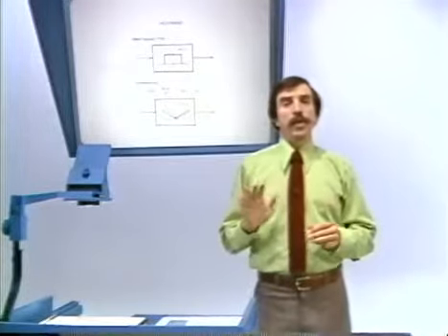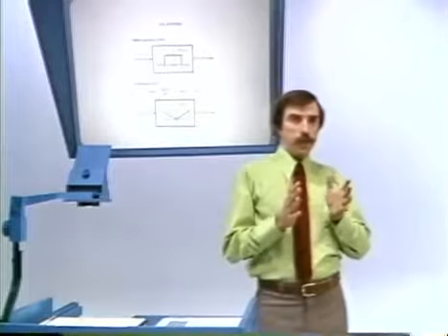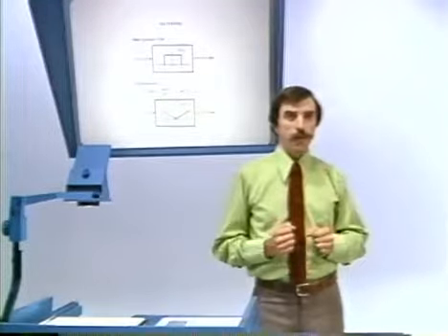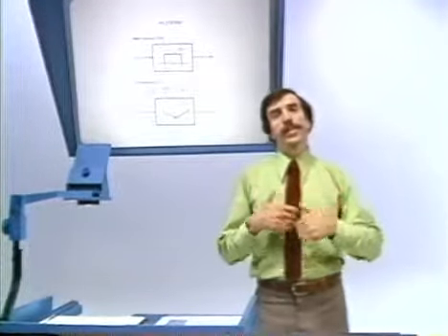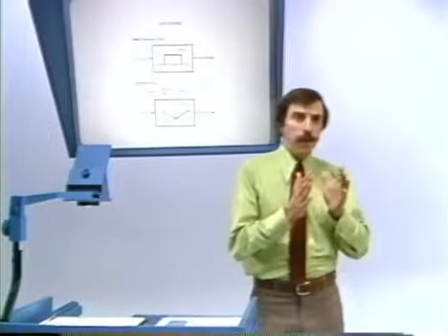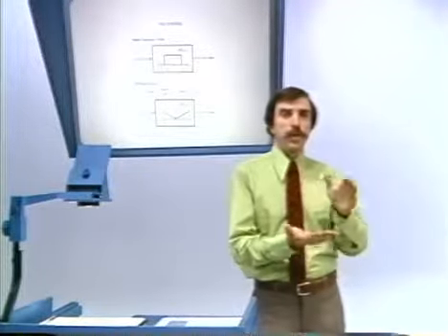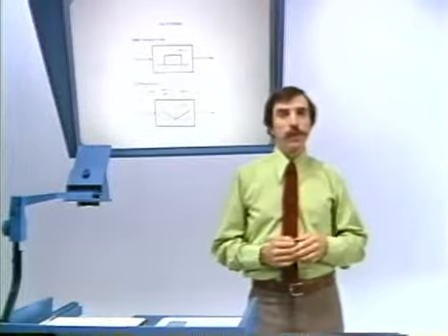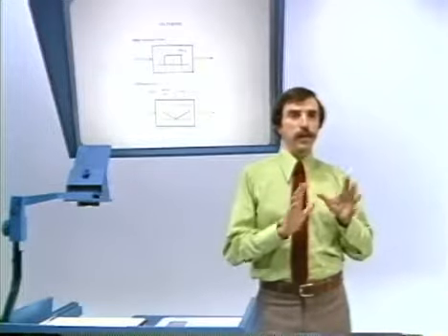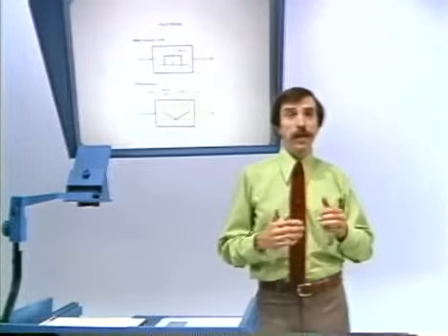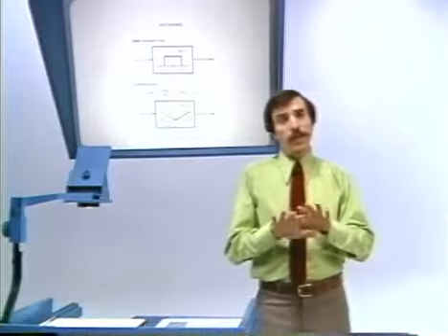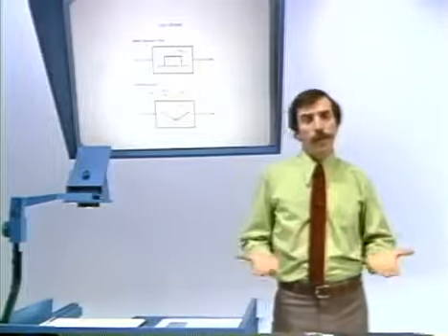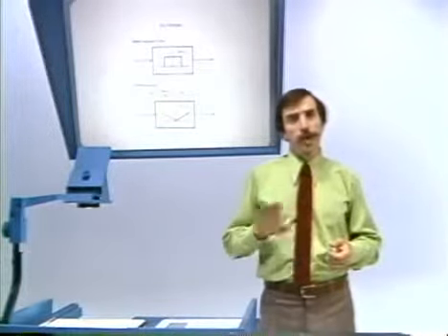When we talked about square waves and we saw how the Fourier series built up a square wave, we saw that it was the high frequencies that were required in order to build up the sharp edges. And so either viewed as a filter or viewed intuitively, we would expect that the differentiated image would in fact attenuate the slowly varying background and amplify the rapidly varying edges.